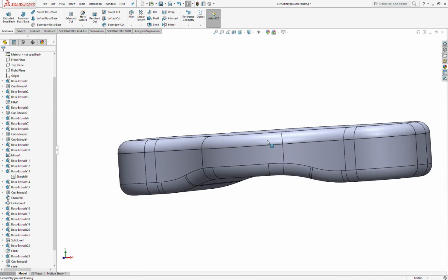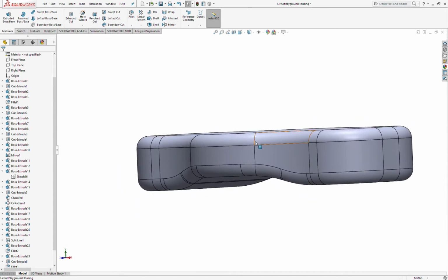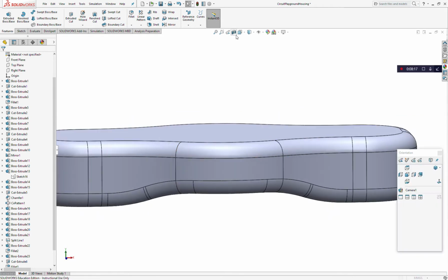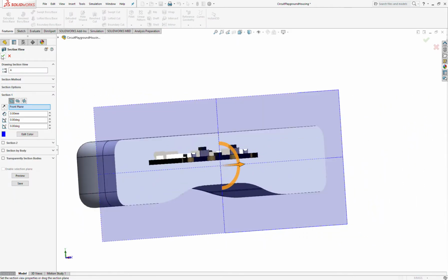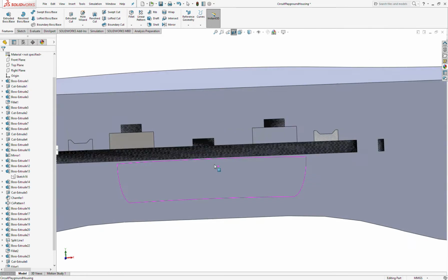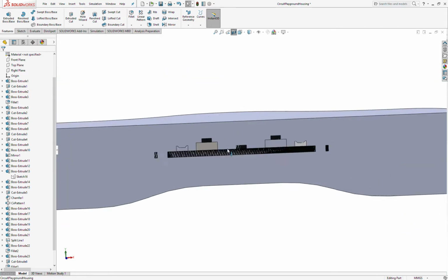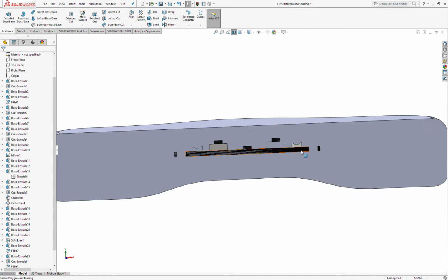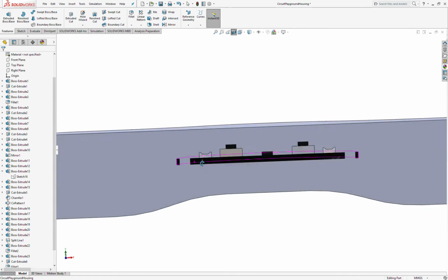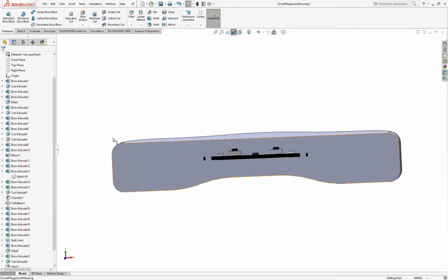So the next thing we're going to do is split it, and then we're going to get our mounting features in, then do some buttons as well, and some switches, and some other things. So let's take a look at what the inside of this looks like. We're going to do a section view by just clicking that section view up at the top. So now we have a section view, we can see where our board is sitting in this. And I think we'll just split along that top plane, which will be just fine for this design today.